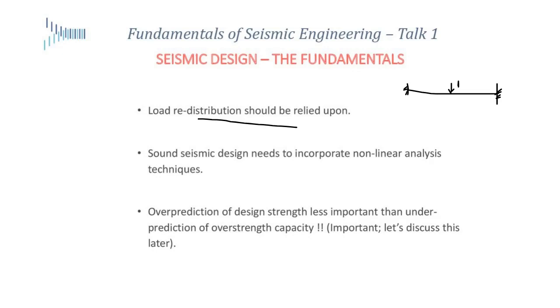Right now, I could, as I had done before, design this for just my elastic envelope. But if I were to actually keep increasing this load, at some point, this point would hinge. Okay, it would reach its plastic moment capacity.